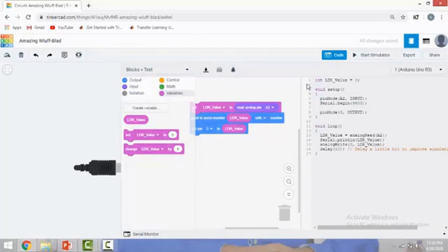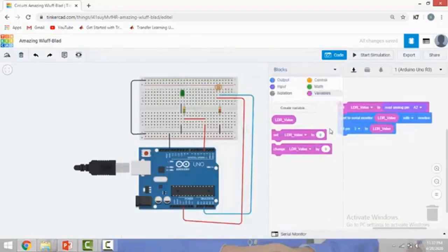One more thing you have to bear in mind. The analog input is going to read from 0 to 1023 only. Suppose you have an analog value more than that, you have to do the mapping, that is, minimum value to 0 and maximum value to 1024. It depends on your requirement. It may be any range, but it will be mapped to 0 to 1023 only.